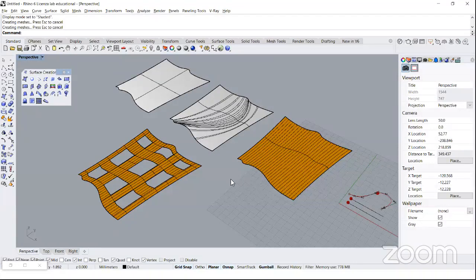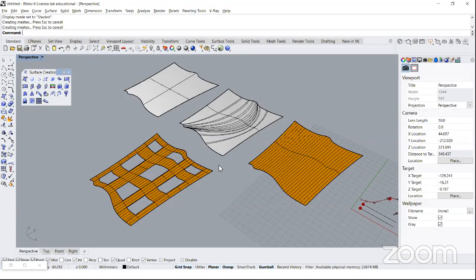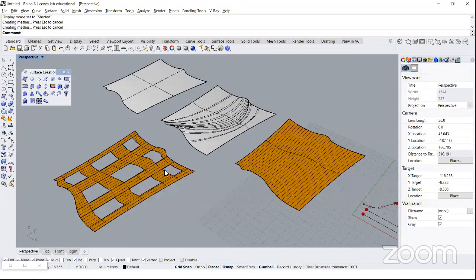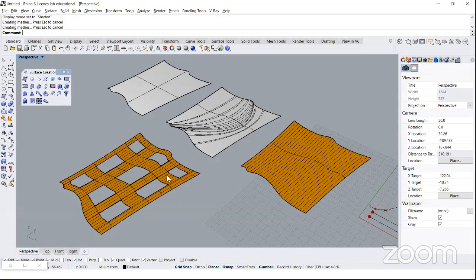This is important to control. It's another important topological consideration on NURBS surfaces because you don't want to see the negative face of a surface unless you really want to. Okay, so normally you want to see always the positive orientation, the positive face of a NURBS surface.